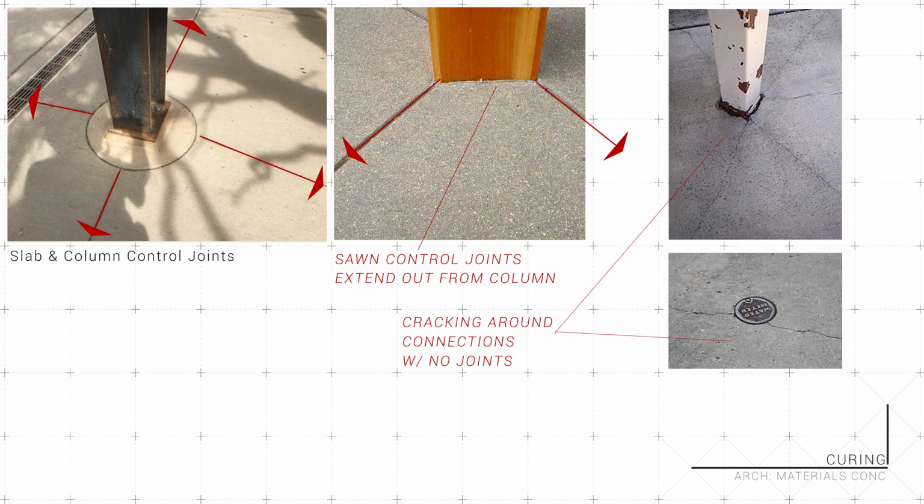So, like these at first seemingly aesthetic cuts, seams that radiate out as lines cast from columns or extruding geometry are control joints as well. Otherwise, slabs are prone to crack at interruptions in their geometry. And you can see too, by these cracks radiating out from the column and water meter, the sawn control joints follow a similar path as the cracks, albeit looking far more regular.